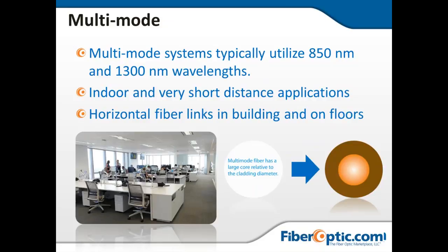So these are all accurate depictions of events that we would potentially see on an OTDR trace, but I think there are always a few other things that could be added here and are probably more indicative of what we would see if we were looking at a trace on a true OTDR versus just a graphical representation. So those are things to look at. And when we're talking about the OTDR and selecting it, the accuracy at which these OTDRs can read these reflective events and how much reflection is coming off these events is a huge factor.